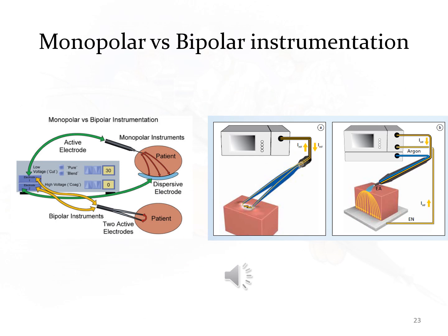Advantages of the bipolar operating technique. 1. Current flows through the tissue between the two electrodes, that is, through those areas where the effect is desired. 2. The danger of inadvertent burns to the patient coming into contact with conductive materials is negligible during an operation with bipolar technology. 3. No stray current. 4. It has reduced influence on cardiac pacemakers.